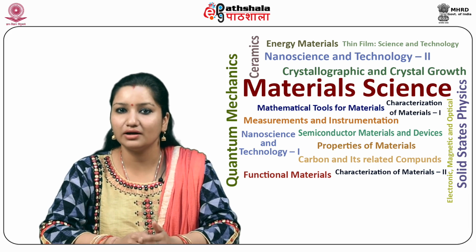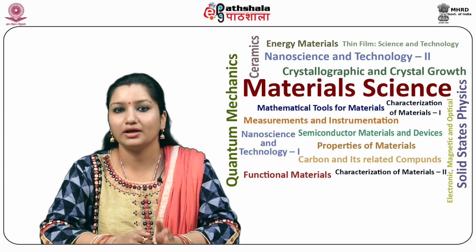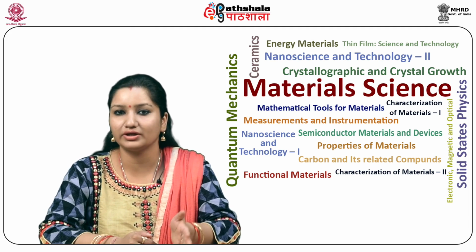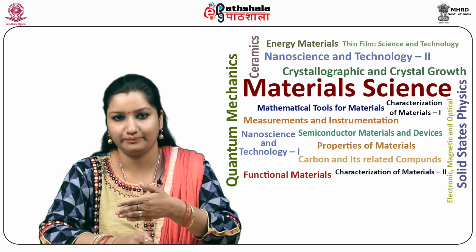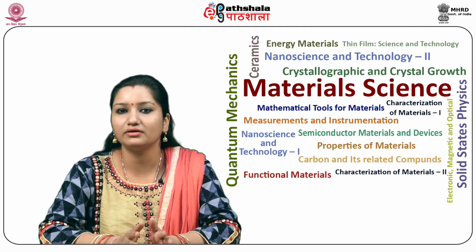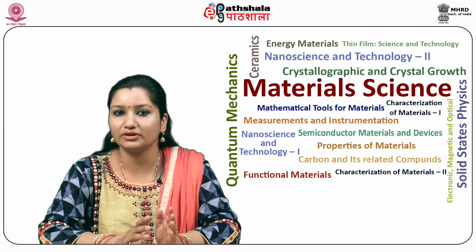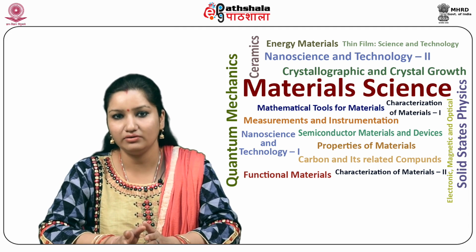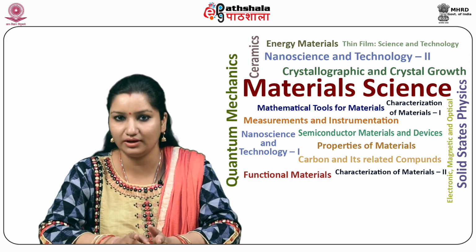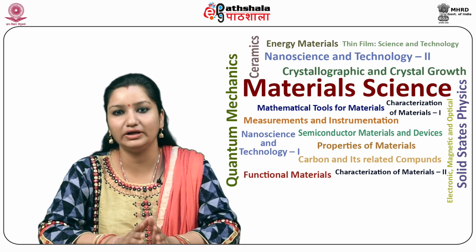Magnetoelectric effect in layered structures provides an alternative, exhibiting higher ME effect due to mechanical coupling between the piezoelectric and ferromagnetic layers. The figure shown here shows the mechanism in a direct magnetoelectric effect in which you can see the coupling between the magnetic layer and piezoelectric layer, in which the magnetic field, that is H, is converted to S, which is strain, then to T, tension, then D, and then finally into the electric field E.